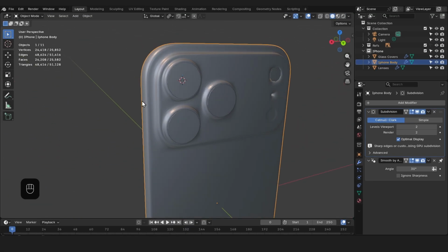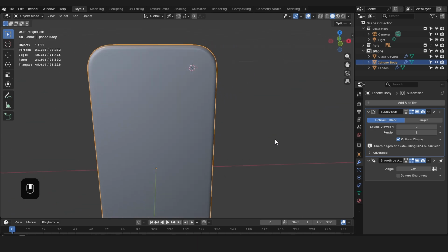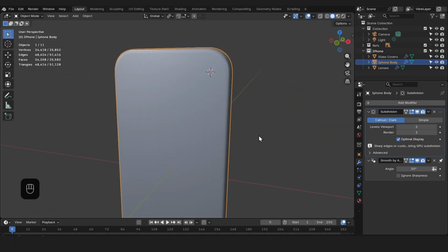This will definitely look horrible right now because when you're using the subdivision surface modifier, you will naturally need to add supporting edge loops so that everything will look smooth, but also the things that need to be sharp should look sharp. Later in the course, we will have a dedicated video for adjusting and sharpening all the different angles of this model. But for now, I just want to apply this subdivision surface modifier so that we at least can start to see a very smooth shape and we can adjust the shape of the buttons based on the subdivision surface modifier.